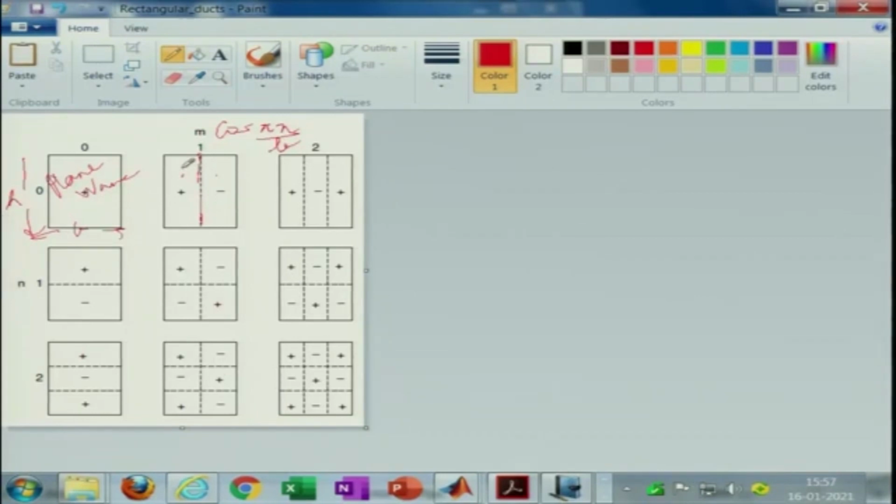As we go for higher solutions, if you consider 2 here, and measure things from here, gradually the phase shifts from plus to negative and again goes back. So, you have two nodal lines. It divides the rectangular cross section into regions of alternating phase, from plus to minus, minus back to plus. These are called modes along the x direction.